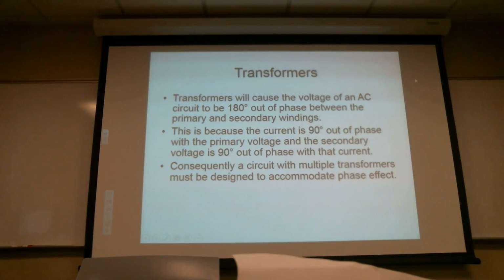Okay, so I go out here and I've got this transformer, let's see, T4 over there and T5 there, T2 there, and they're all kicking things up to 480 volts. Those are all taking everything 277 to 480, and they're doing it in 3-phase.